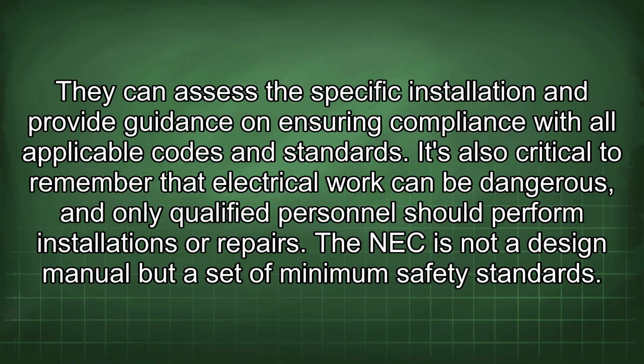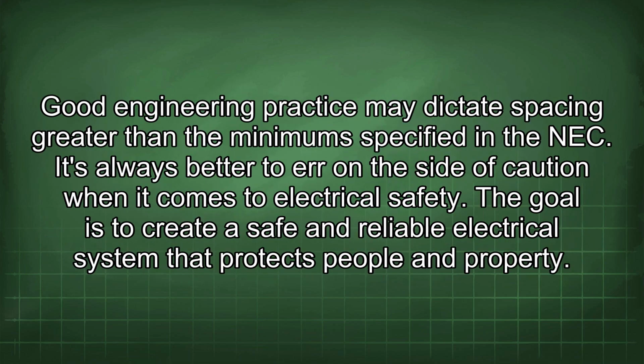The NEC is not a design manual, but a set of minimum safety standards. Good engineering practice may dictate spacing greater than the minimum specified in the NEC. It's always better to err on the side of caution when it comes to electrical safety. The goal is to create a safe and reliable electrical system that protects people and property.